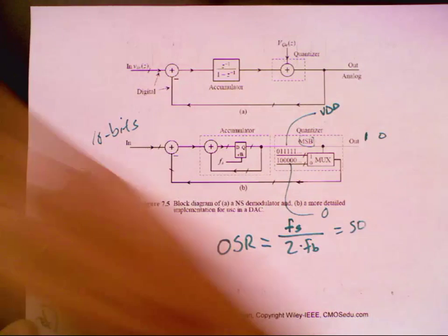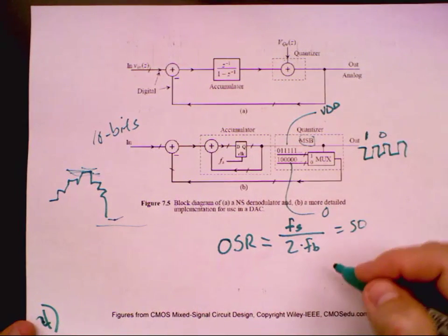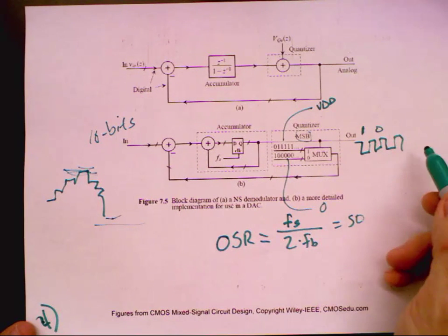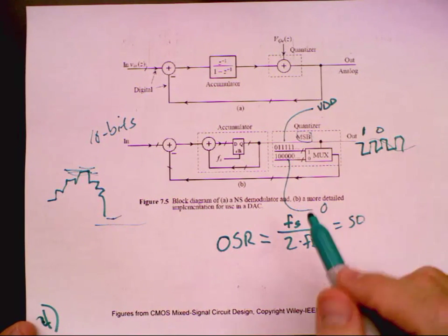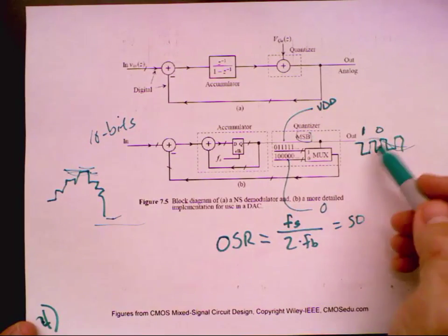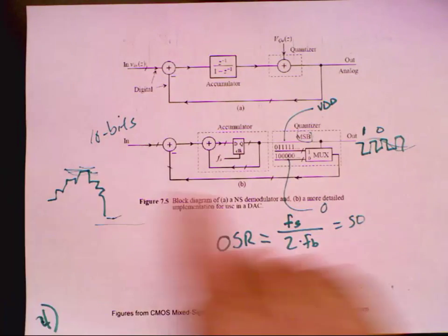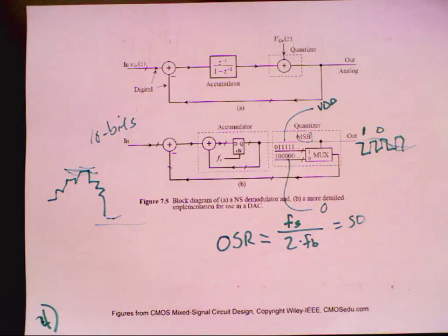Well, remember, it's a 1-bit code. How do I cheat in my simulation so I don't have big digital filters? Yeah, I use a filter. So I use a filter and then it averages. As we just saw, you can average that and then you get an analog, and the better you average, the more it resolves. So everybody follow. The whole point here is I don't want you to think that sigma delta is just for analog to digital conversion. You can also use it for transmitting data. Questions?